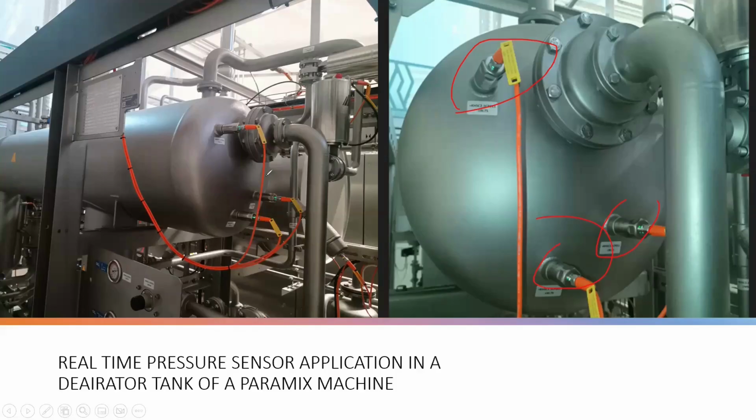You can see they are connected directly with cable, which goes over to the input card and then transmits the information, like I said before, to the programmable logic controllers. So the hydrostatic pressure gotten from the sensors is transmitted to the programmable logic controller. The logic controller itself acts on the information transmitted by the sensor.